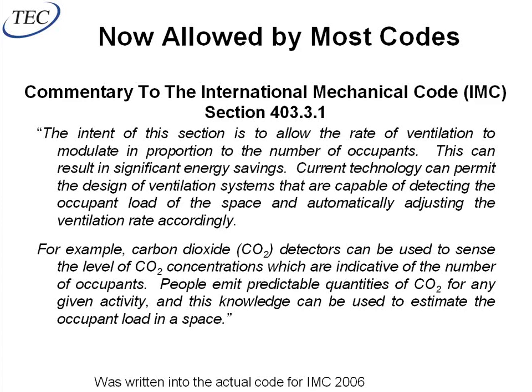This is what it looks like in the International Mechanical Code. I won't read it to you, but the language between the International Mechanical Code and ASHRAE 62 is basically identical. And you can see here it actually calls out CO2 specifically as an acceptable way to do demand-controlled ventilation and reduce the air below the code required air.